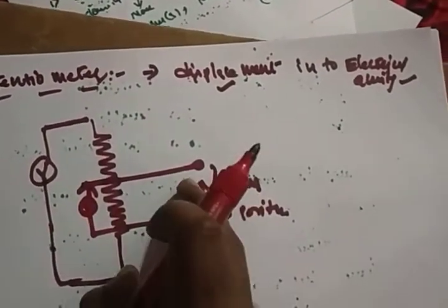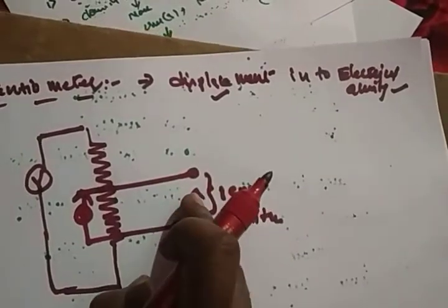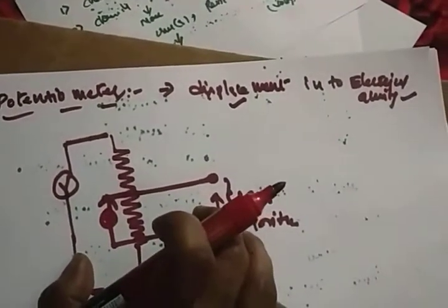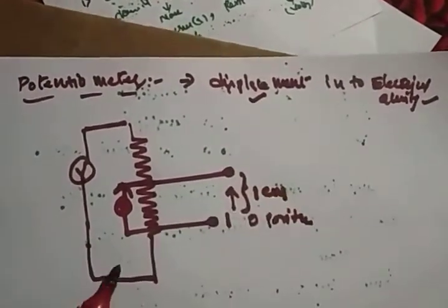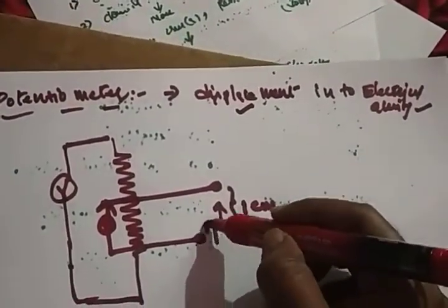Why did this voltage come? By moving this, whatever the length, the displacement is equal to the voltage developed across the changing resistance. So that is called a potentiometric transducer. That means whatever linear displacement is converted to voltage, right? You don't have any other method to measure it.